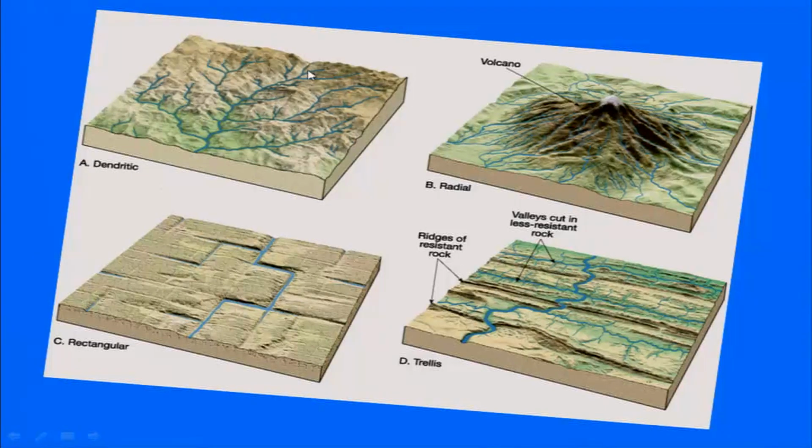If you have, then you will be able to see the dendritic drainage, whereas radial drainages form if you are having domal structures, as we were looking at in the previous slide. So if you are having the elevated portion in the center and sloping surfaces on either side, it will result in the formation of radial drainages. If you are having fractured rocks, and you are having high-angle fractures, maybe almost at right angle, then you will be able to see rectangular drainages.